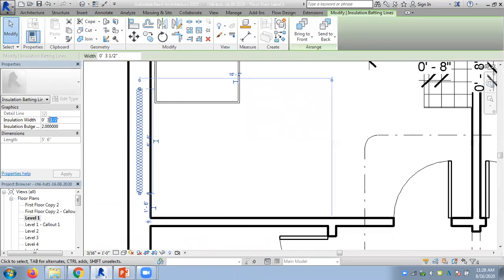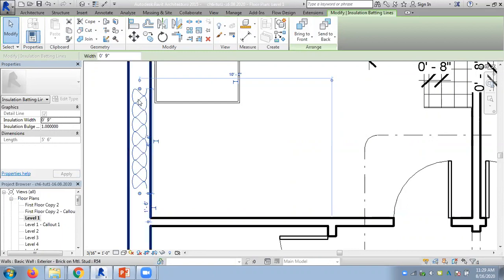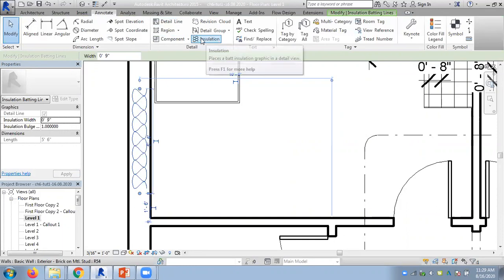So if I just have it like 6 inches, it will be increased. And the gap here I can change, say 5, to be very much closer to each other. These are not 3D models, just 2D AutoCAD kind of drafting drawings. So if you see this kind of a symbol in a Revit model, this is insulation applied from this insulation tool. And we have 2D text.